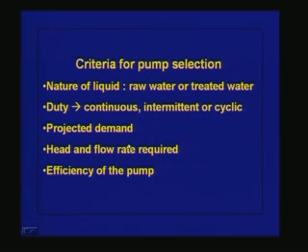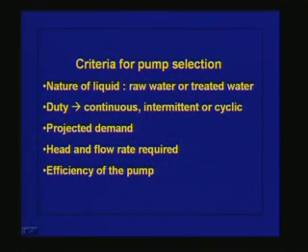We are going to have this pumping operation over a long period of time, maybe for 20 years or 30 years, and we may be operating it for maybe 12 hours a day or even 24 hours a day. In such cases, power is required to operate these pumps, and not all the electric power that we supply to the pump is converted and 100% used in lifting the water. So the efficiency comes into the picture. The efficiency of the pump should be very high so that the power consumed during the pumping operations is minimized.